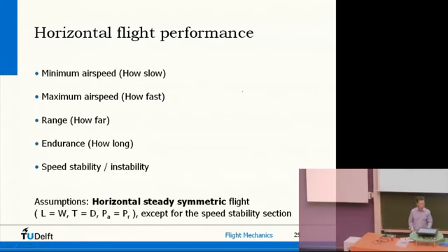Now that's an important thing to be aware of as a pilot, and it's fairly easy to solve with our equations of motion. Like I said, we're considering horizontal, steady, symmetric flight. So lift is equal to weight, and thrust is equal to drag.